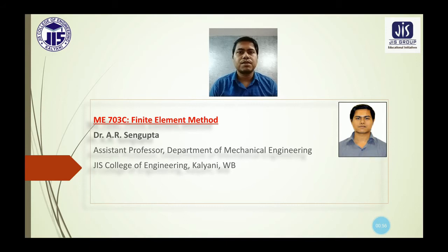Then we have discussed in detail the concept of discretization, then the numbering of nodes, then the implementation of the boundary condition. After that, the material properties, then the calculation of the stiffness matrix, then the post-processing part where we will calculate the result. So all these different steps we have discussed earlier in detail.